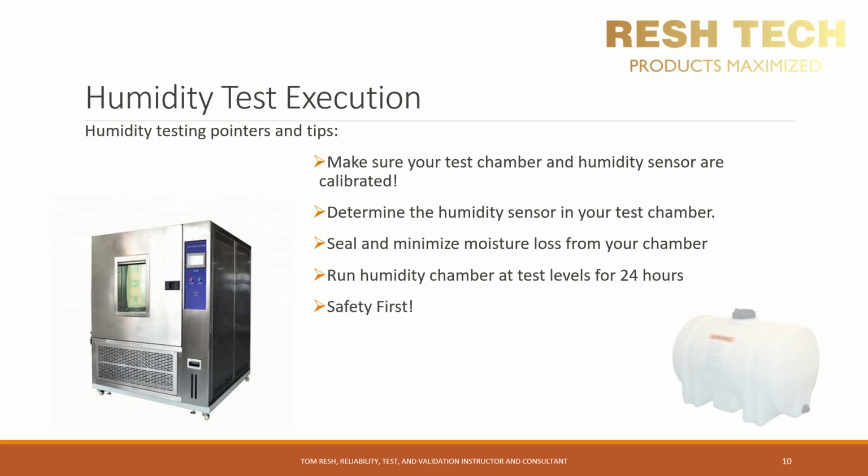A quick note, you should always need to consider the water supply for your humidity chamber. If you have a RO or DI water from your facility constantly being supplied to the chamber, this is not an issue. But if your chamber has a tank that needs to be filled to maintain water supply to the steam generator for your humidity chamber, you need to have a periodic check in place to make sure you have water in the tank, or your chamber will abort the test and cause one of the issues mentioned in the 24-hour pre-test check pointer. Also, make sure you're using RO or reverse osmosis water, or DI, aka deionized water, as the water impurities in tap water can damage your chamber.